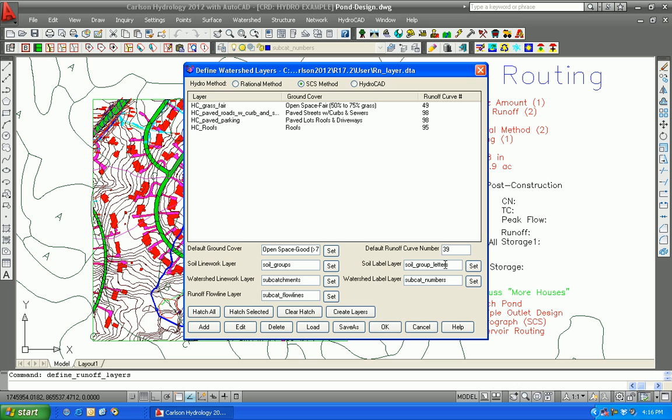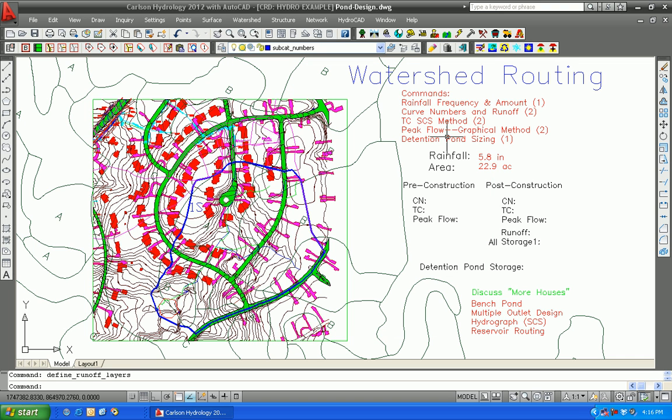And finally went to the HydroNet Explorer, which used the lower items to actually find the watersheds by layer designation, including the longest runoff flow line, and from that it computed the peak flow in one step. And when that's done for both before and after construction conditions, that leads to accurate detention pond sizing.